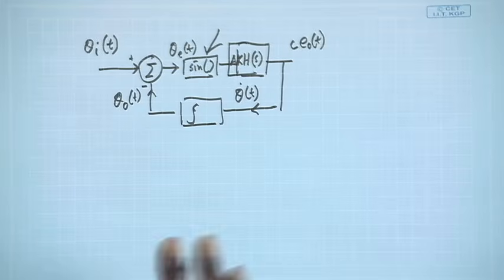So in the next class we will try to see how to get rid of this. A very simple assumption will get rid of it. We will say we are doing a small error analysis. That means the VCO has already almost tracked it. Generally, if I have a carrier signal, I will give an input which is very close to the carrier, because it cannot be that I have a carrier coming at 5 megahertz and I am just starting from 1 megahertz. I will never do that, because I know roughly it is 5 megahertz. So the VCO free running frequency will already be around 5 megahertz.